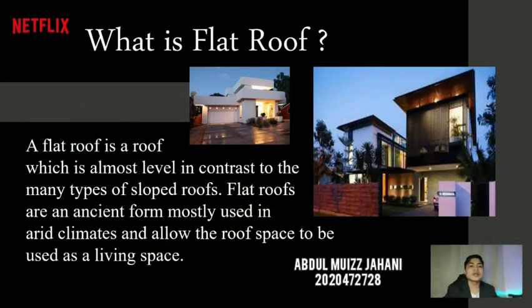What is a flat roof? A flat roof is a roof which is almost level, in contrast to the many types of pitched roofs. Flat roofs are an ancient form, mostly used in arid climates, and allow the roof space to be used as a living space. It is the cheapest to build but will cost you much more than other roof types in maintenance costs. They have a minimum inclination, generally between 2 to 3%, sufficient only to guarantee the flow of water down to the drains. This type of roof surface can be workable, increasing the usable area of the building, or not workable when only accessible to maintenance staff.